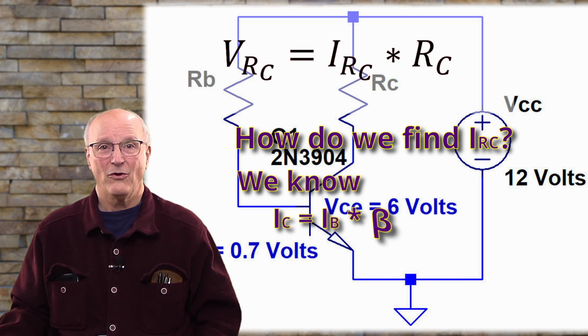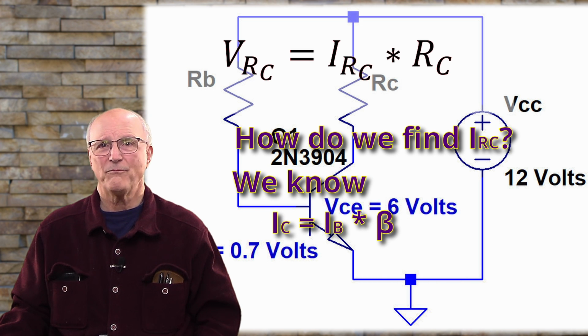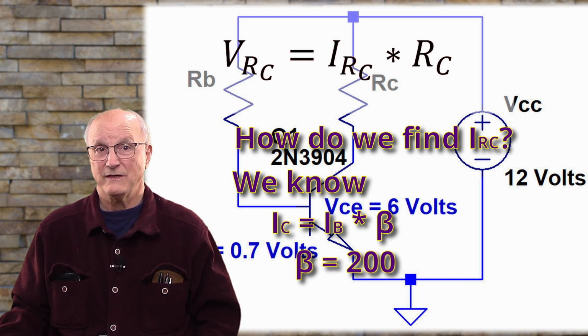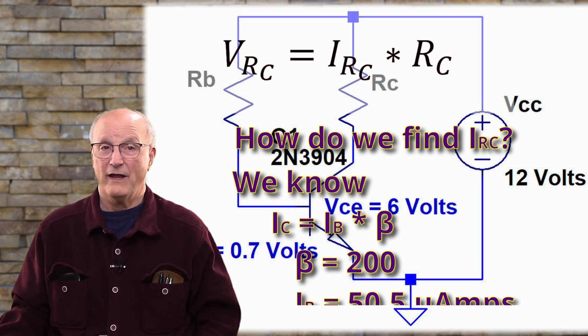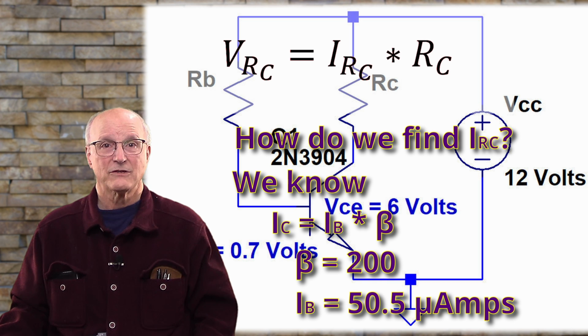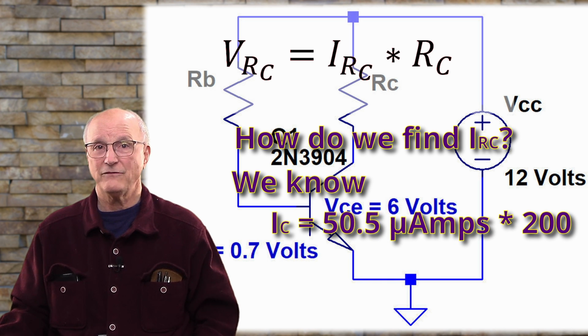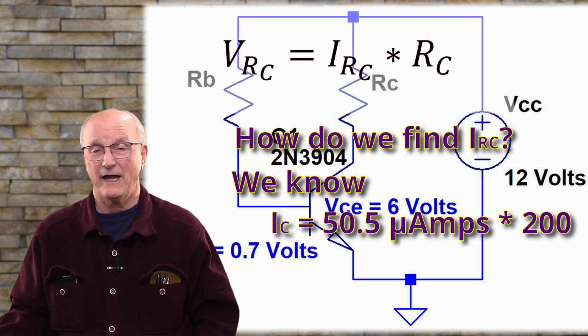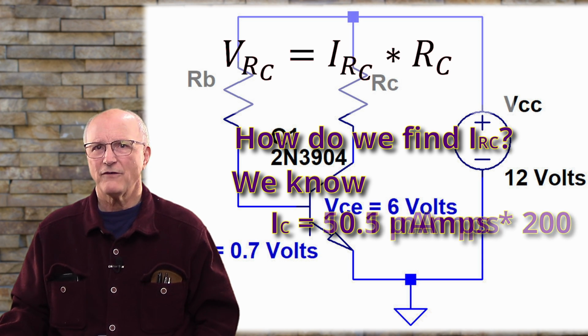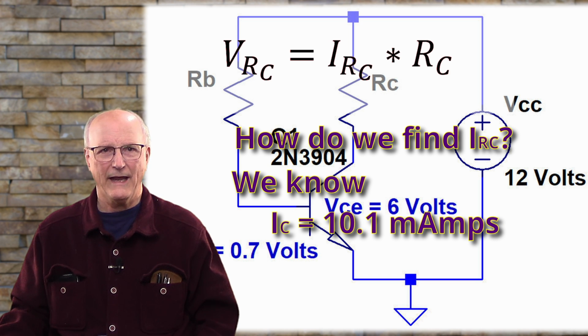Well, we know the collector current is equal to the base current times the DC current gain. And we know that we have a DC current gain of 200, and we know that we have a base current of 50.5 microamps. So the collector current is equal to 50.5 microamps times 200. So we have discovered that we have a collector current of 10.1 milliamps.